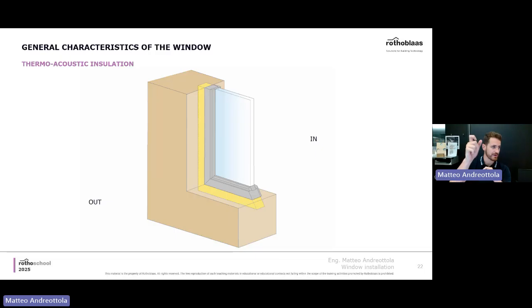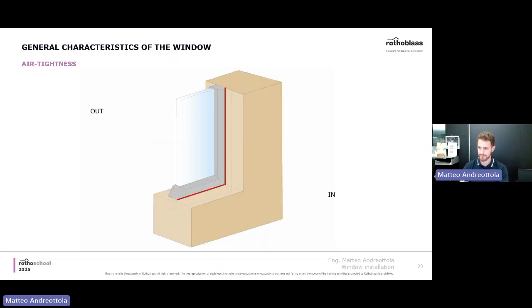With foam, you'll never know if the foam is enough, if you've placed the foam all around the profile of the window, or if not. This is why I tend to prefer expandable profiles.